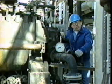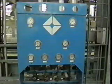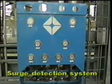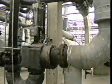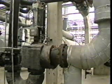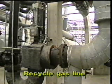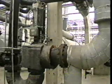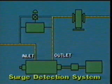That's why you'll find most compressors use a surge detection system. The surge detection system senses discharge pressure variations and initiates a compressor shutdown in the event of a potentially serious condition. A surge control system can also be installed that allows discharged gas to be recirculated outside the compressor to the suction side. The objective here is to keep the flow above the surge point.